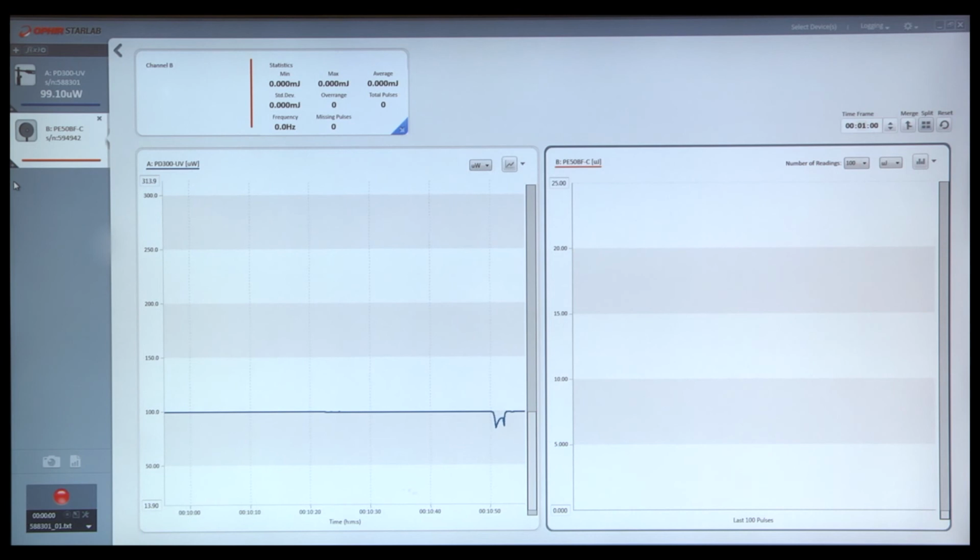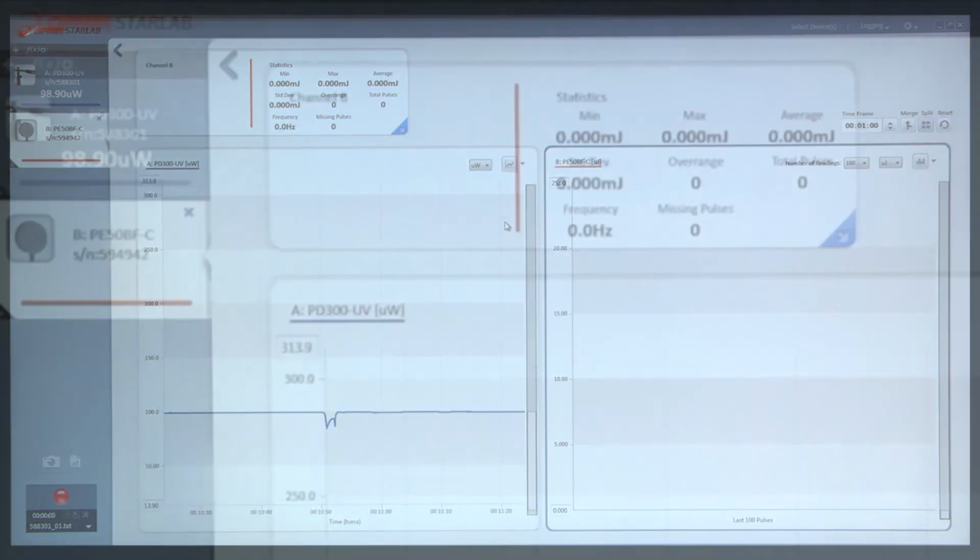And we can add a number of channels. Usually we define the maximum as about 7 or 8, but in principle one could go higher. Clearly more than 4 windows would not be very useful in terms of an operator seeing what one is doing. One can perform data logging with multiple channels simultaneously, and all channels will appear in the log file, both in the log viewer format and in the text format or exported to Excel.